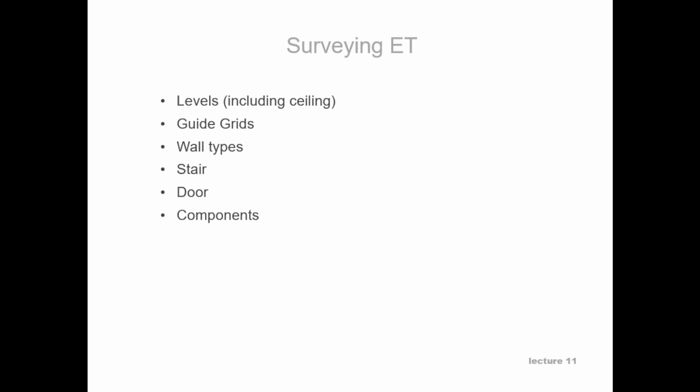If you're surveying a stair, again, understand the shaft size, that overall shape. In engineering technology, it's a rectangle. And then observe whether or not you have any shafts, or if the landings on each level abide by that overall shaft size. You're going to note the number of risers, the length between the door and the first riser, the depth or the length of the landing, the height of the landing, and the height of the finished floor from level 1 to level 2 in our case.